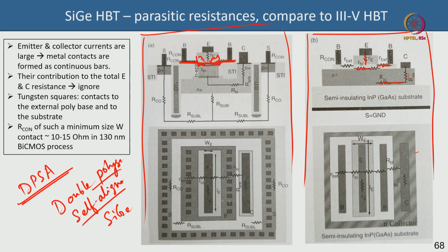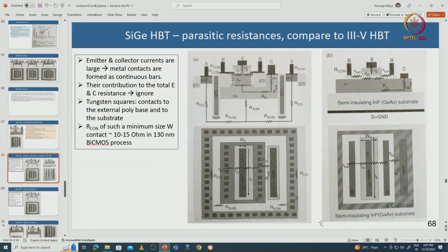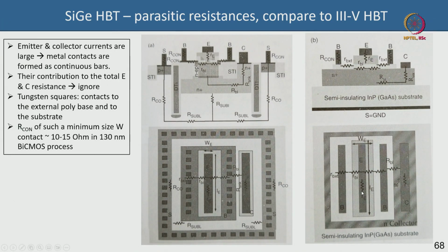But anyways, for this particular discussion, what we need to remember here is that there are different resistances here. Of course, there is an emitter resistance, the intrinsic emitter polysilicon resistance, and the emitter metal to polysilicon contact resistance. There is this intrinsic base resistance inside the silicon germanium base, then there is this extrinsic resistance in the polysilicon. There is also an extrinsic resistance below the oxide spacer. There is the sinker resistance here, which should be low, of course. Then there is this lateral collector subcollector spreading resistance here, right. The substrate resistances are of course there, which we are not talking about, but we should.